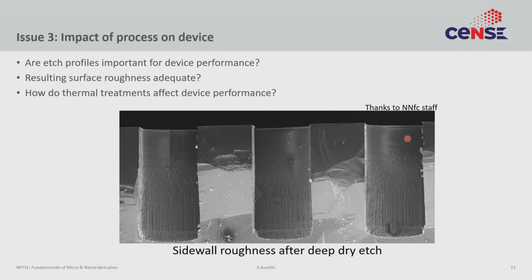If you are in the back of the line, you should probably use some sort of dry etch to clean organic contamination, or use solvents, and not an RCA recipe, right? Those are the kinds of things you have to always remember. It uses the basics that you have learned from your unit processes in this course, and you use those same concepts, but you have to remember to apply them when you are doing the process integration.